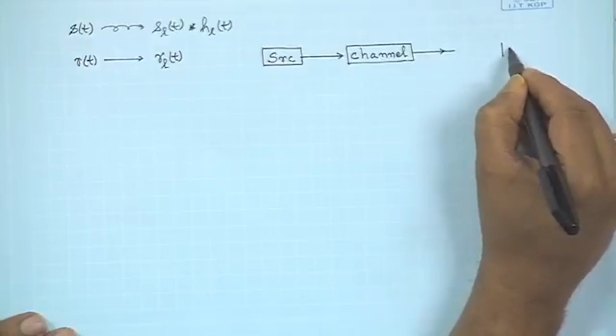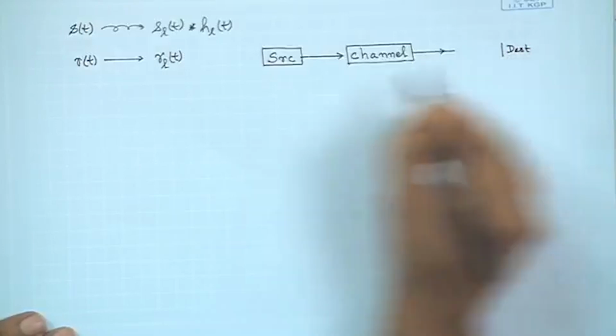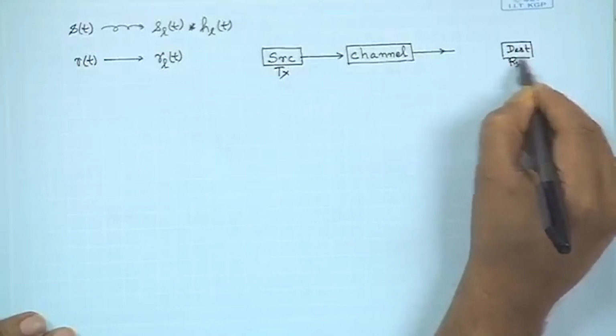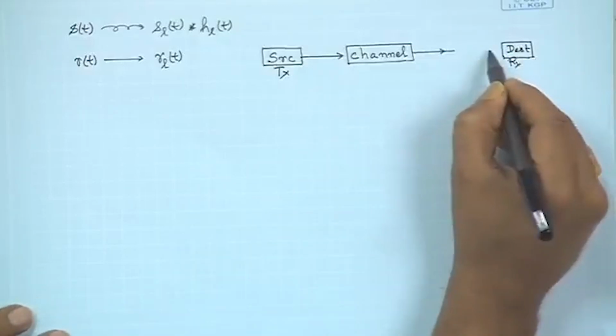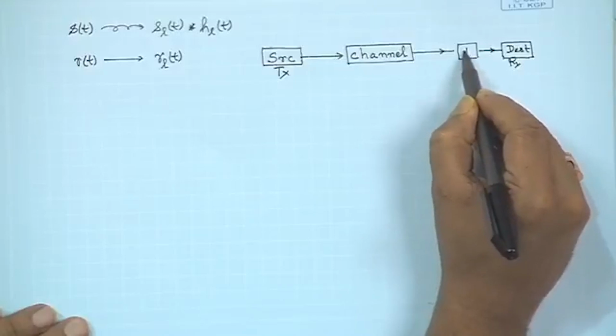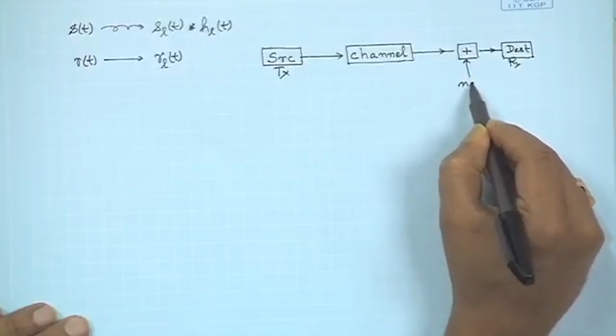Now then there is the receiver or the destination. So it's good to call this the transmitter, and this the receiver. Probably we have said before, or we can say now also, if you look at the several receiver components, there will be filters, oscillators, low noise amplifiers, and so on and so forth, which have several passive as well as active components. Now these components generally add noise into the system, and in one of the well accepted models, there is additive noise present in the system, right.